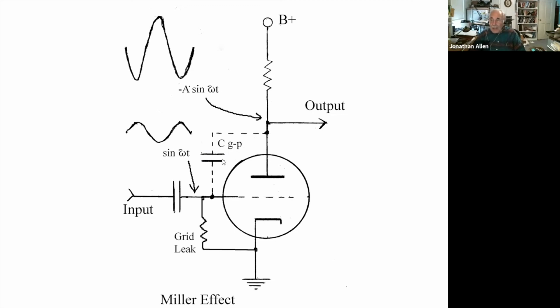Now, radio kept wanting to get to higher frequencies because there was more bandwidth that you could exploit. You didn't have to remain in the crowded low frequency channels, and the higher frequencies had the advantage that they could cover long distances. But anyway, the remedy came in 1926 when a fellow named Dr. Albert W. Hull and his colleague N.H. Williams at General Electric put a shield or screen grid between the control grid and the plate to create the tetrode. That means 4 elements now, right?